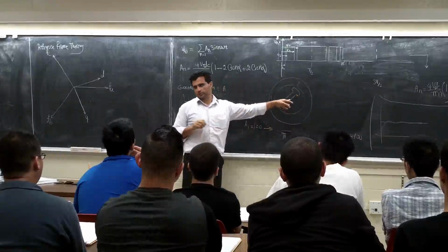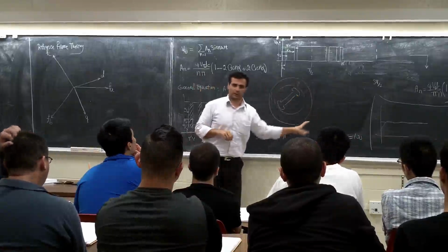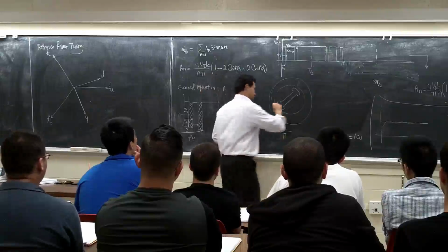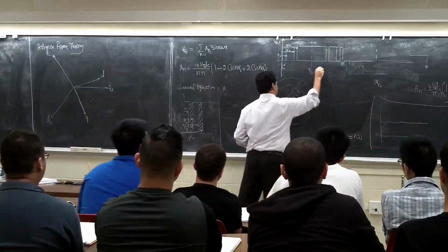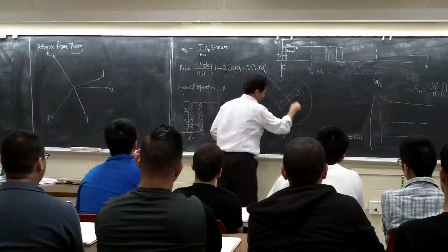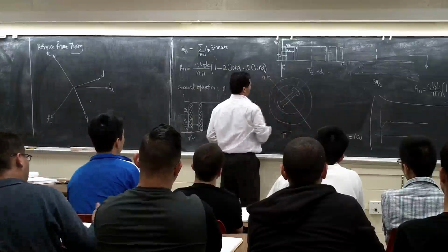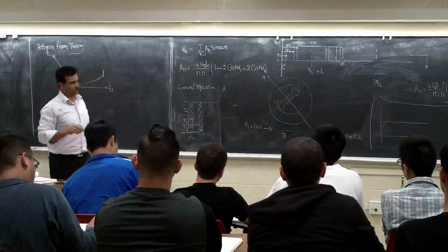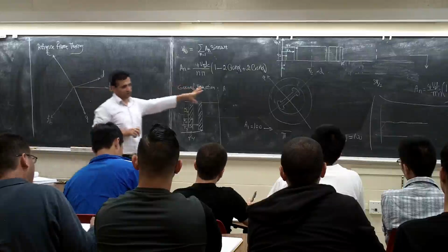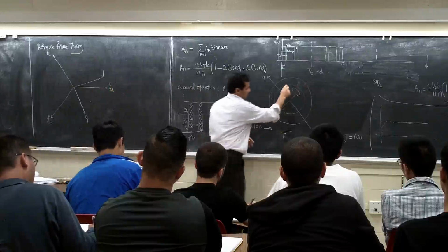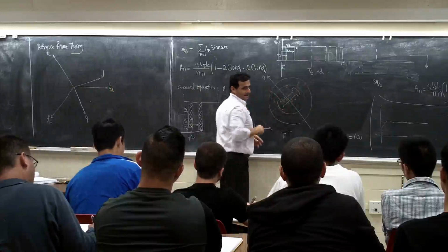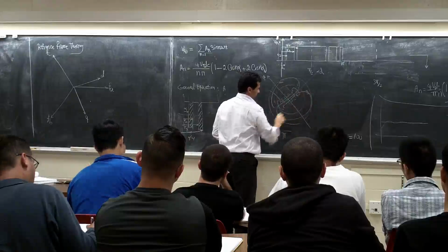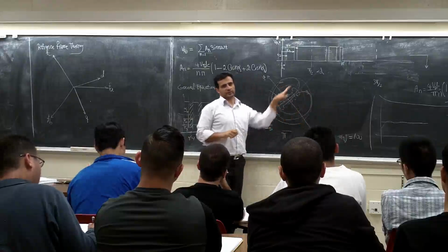This is the rotor of this machine. They call it salient pole because it's not cylindrical. Remember the DC machine and induction machine had a cylindrical rotor. But here, they call this one the direct axis, D axis, and this one the Q axis. Hopefully, the year after next, we will offer a course on AC machine drives, and we'll talk about all this. But this idea started from here. There's an electric body here, there's a winding here, and there's a flux going like this. They call this one the quadrature axis and this one the direct axis.